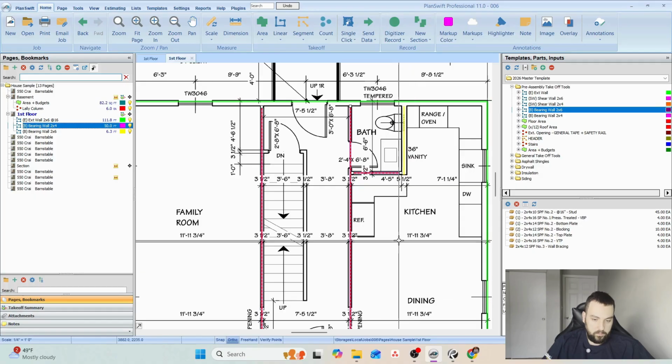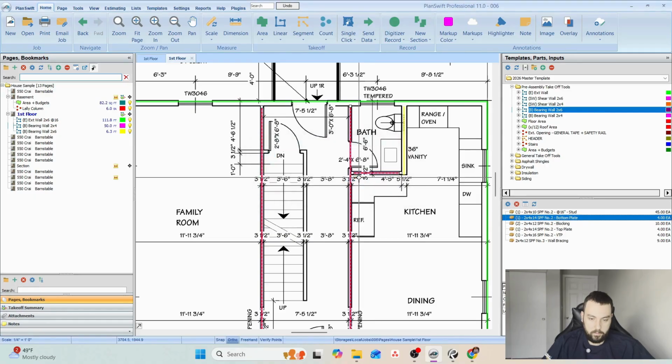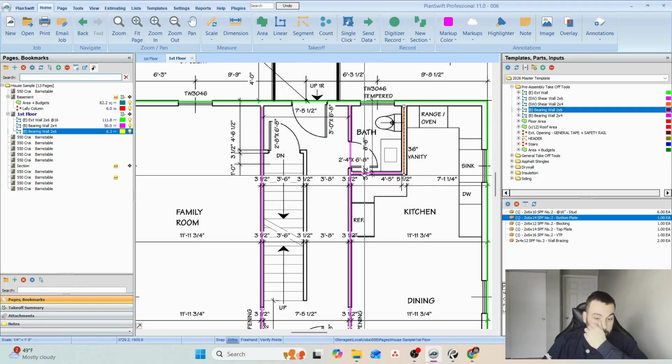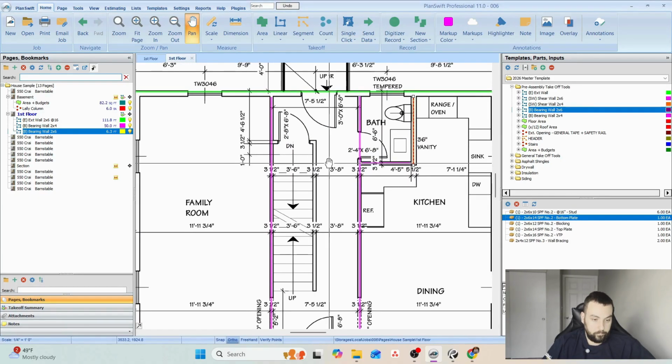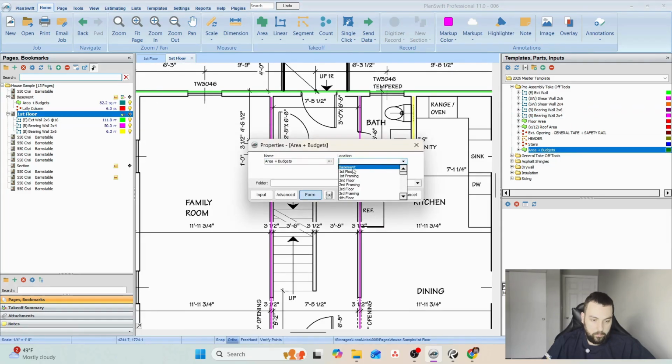The floor is 10 feet, 9, 11.25, so it's fine. No need for pressure treated because we're not in contact with concrete. Blocking is okay. Same for 2x6. Cool. Okay, let's do our thing for the budget.